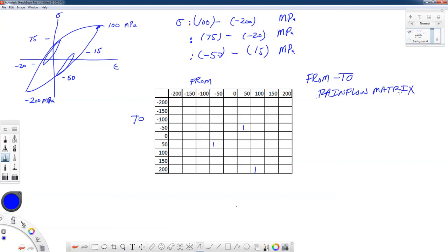These are used sometimes, and it's a way to reduce a very lengthy time history that has a lot of variable amplitude cycles in it into a very kind of single page description of that time history. You can even reproduce time histories with this kind of data. You just need to make sure you have from and to. Now, what is lost in this are any possible sequence effects that you might have. So with any kind of data reduction technique, if you reduce the amount of data that you have, you're also losing some information.